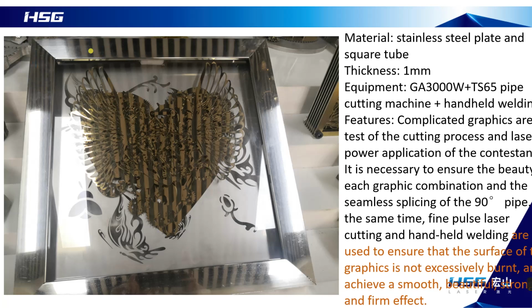The male and female splice is very good, so we need to use a handheld welding machine, spot welding a few times. It can be perfectly fixed together. No wire filling or full welding, just spot welding. The final effect is very smooth and beautiful, but also very solid.